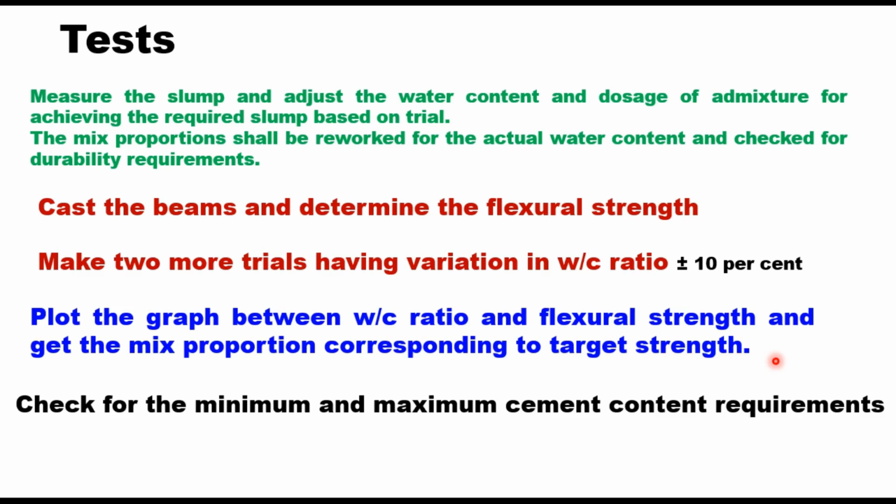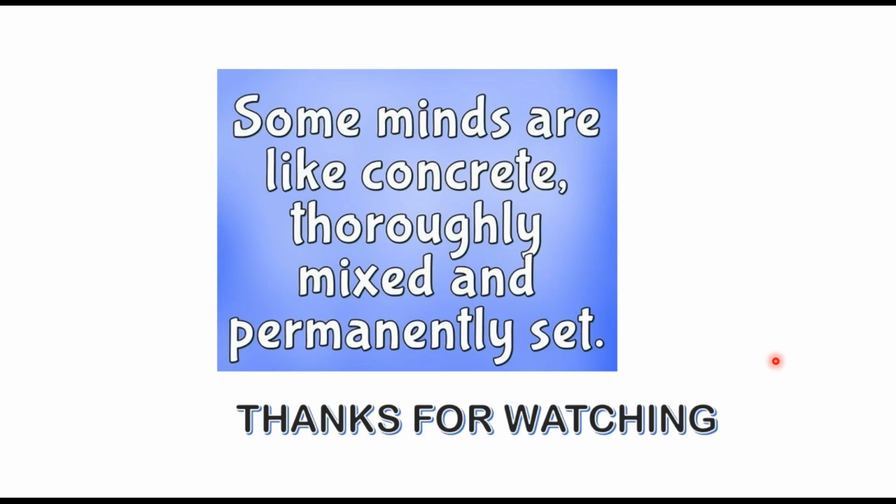Check the minimum and maximum content of the cement as per IS 456, that is 360 to 450 kg per meter cube. So that is how you design a mix.